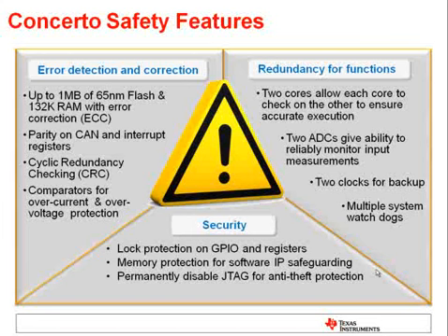Security is on this device to help customers protect against tampering with the system. Locked protection on GPIO registers allows for the registers not to be overwritten during runtime. Memory protection is available so that customers can securely lock their code. Concerto is unique because we provide 2 code security lock zones so that both a third party and the customer can lock their code. We also allow customers to permanently disable the JTAG so no one can try to access via JTAG and read the internal code. The multiple safety features on Concerto MCUs will help customers protect against faults and failures in a system as well as protect important IP.